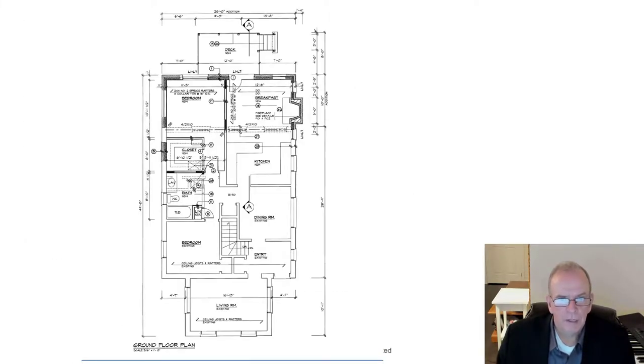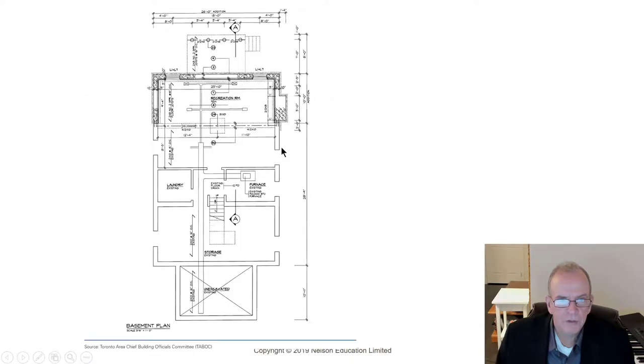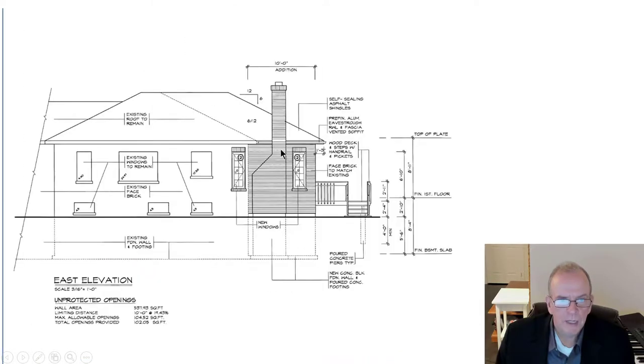So if we're looking at this closely, I'm assuming this window does not really exist, so this is one we've got to cut in. I'm picking up on that because it's the same size as this one. They're going to make it on both sides of the fireplace, so it looks nice and symmetrical. And when I'm looking outside, there you go, there's the two. So I doubt this is existing. It says new window, so that means I'm going to have to cut this out.